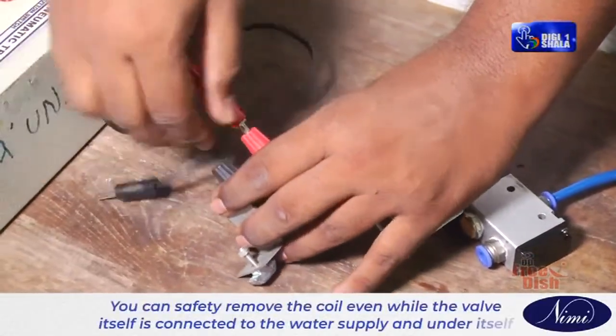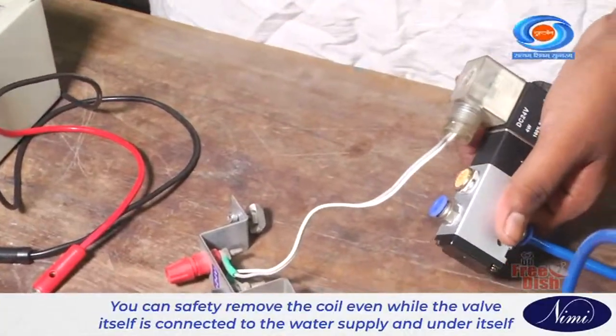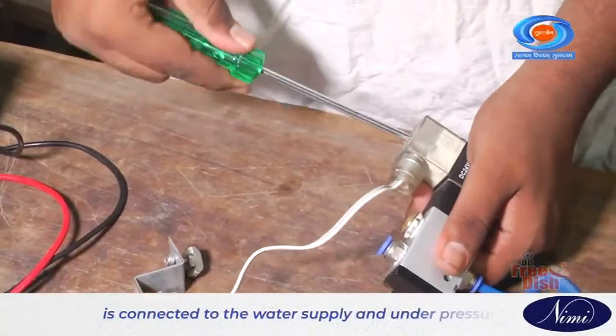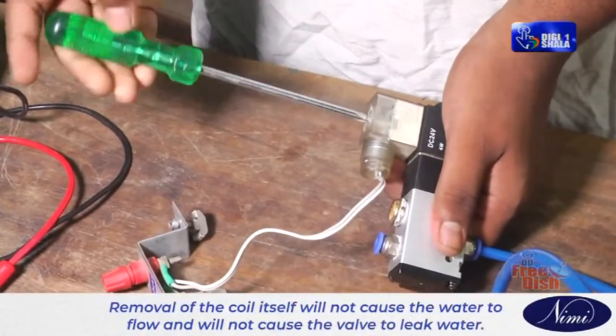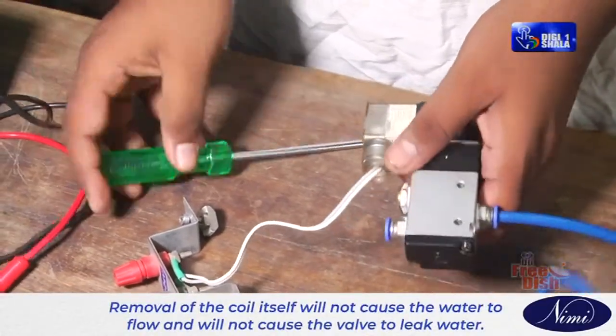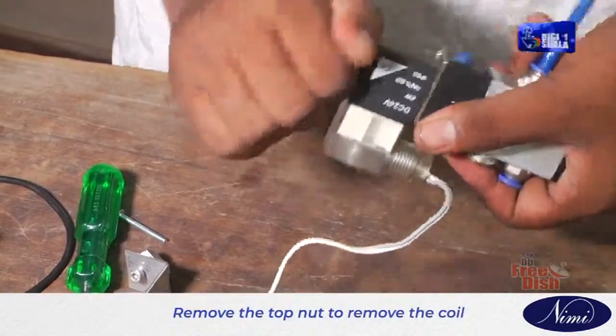You can safely remove the coil even while the valve itself is connected to the water supply and under pressure. Removal of the coil itself will not cause the water to flow and will not cause the valve to leak water. Step 2. Remove the top nut to remove the coil.